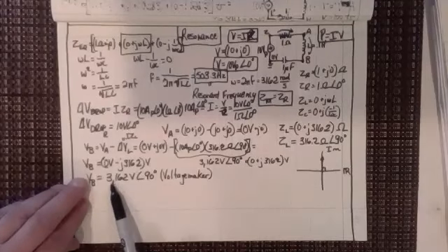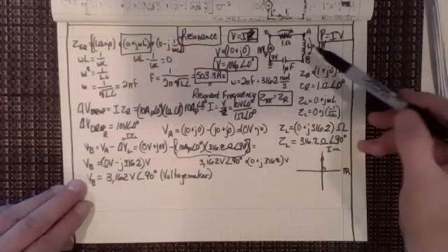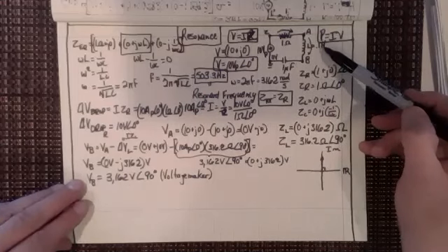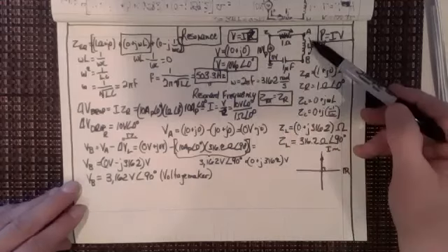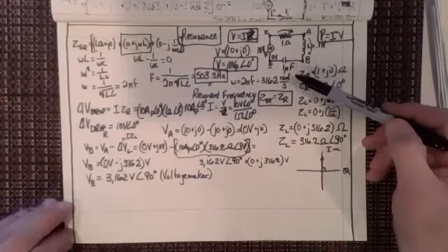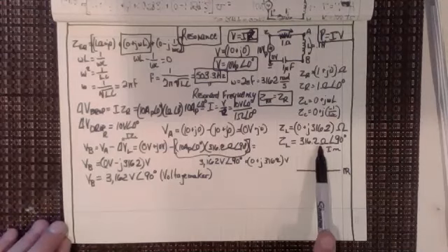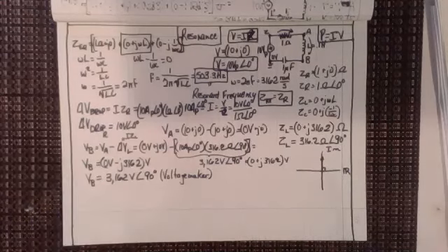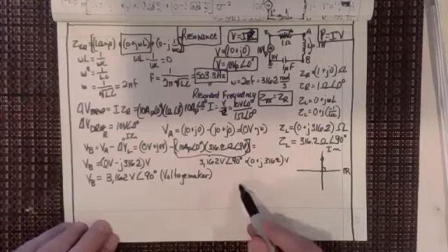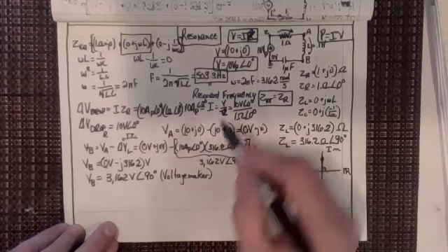But I could get this much higher, couldn't I, by just changing this to a 1 Henry inductor and then running it at a different frequency that would make the 1 Henry and the 1 microfarad better, because in the end, I'm always looking back to this. So you can see how you can change that and modify it. The truth is, there are no perfect inductors. You're always going to have resistance with any inductor because it's wound with regular magnetic winding wire. So that's going to be a problem, right? Okay. So I just wanted to point this out and show you what resonance is.